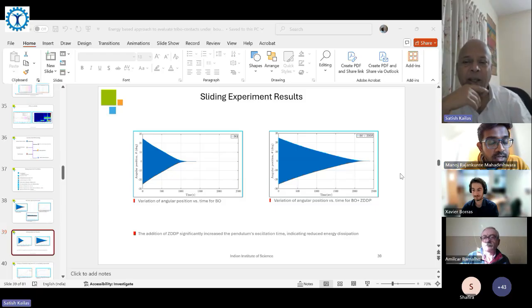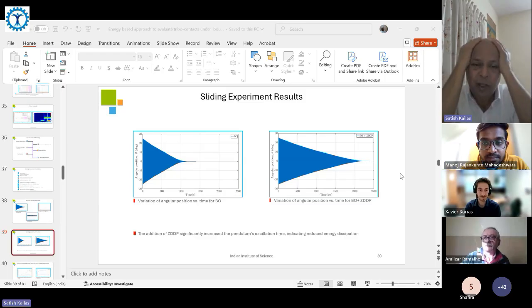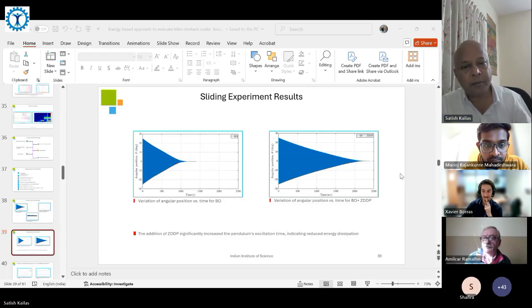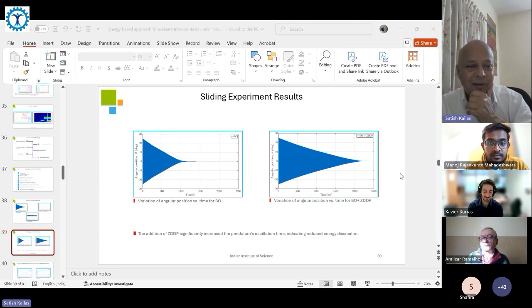In the hydrodynamic lubrication. Yes, that's the question. Hydrodynamic lubrication, generally, you don't expect much wear. See, what happens in hydrodynamic systems, one of the things is that when I stop the machine and start the machine, it goes from hydrodynamic to boundary. And only after a certain RPM will hydrodynamic come. So, for example, if you are using it in a steam turbine and other things, these hydrodynamic bearings are known to last for years.